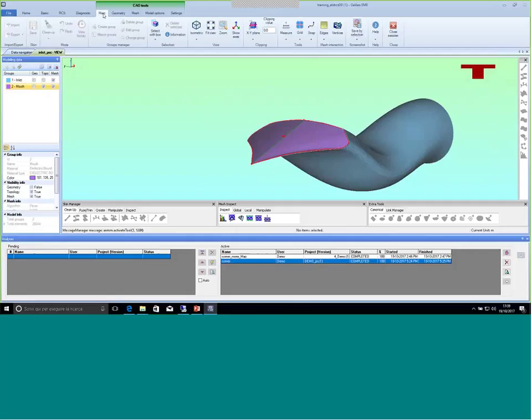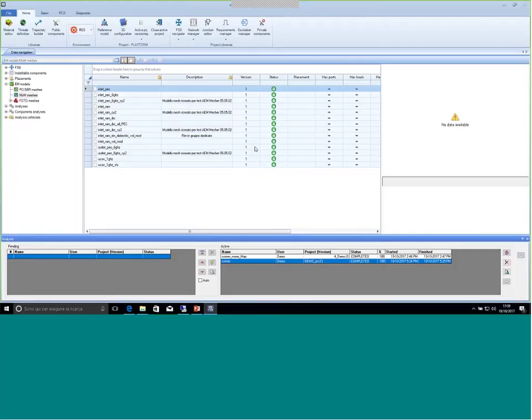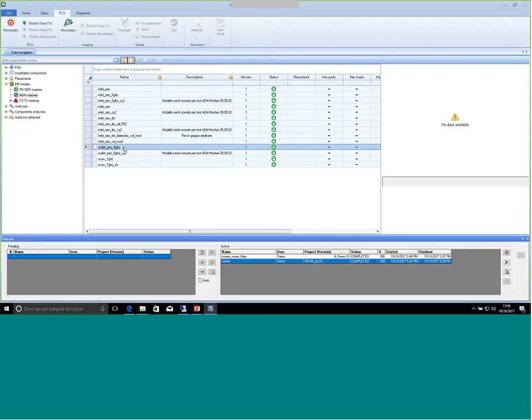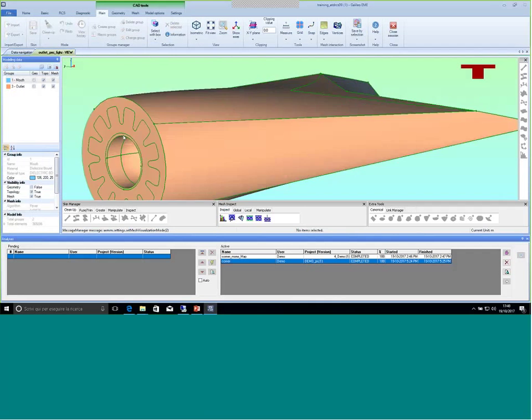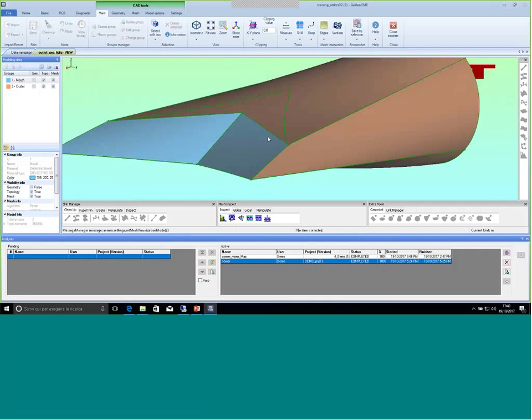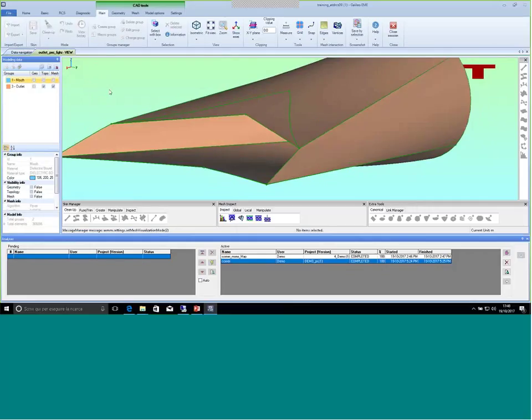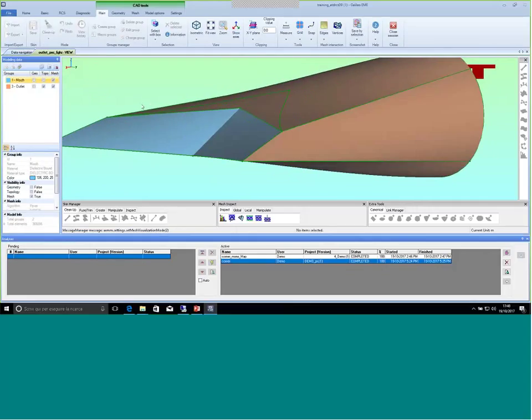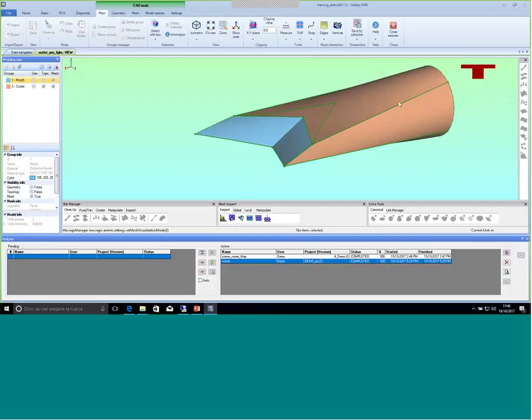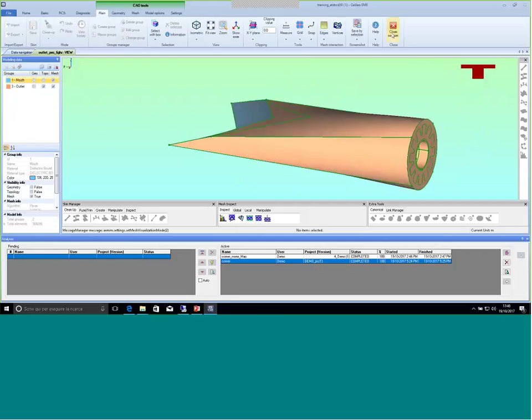In the same way, I have generated the mesh model for the outlet here. And in this case, I have closed the outlet hole with the mouth here, and then I set the cavity flag inside this structure.